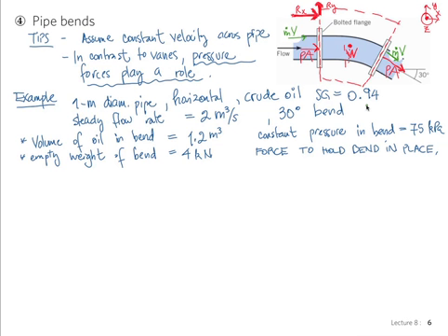So we have pressure forces and reaction forces at the flanges, and we have flux of momentum in and out, plus the weight, which we need to consider eventually for the resultant, but it's not going to be affected by the momentum fluxes because they happen in different directions.